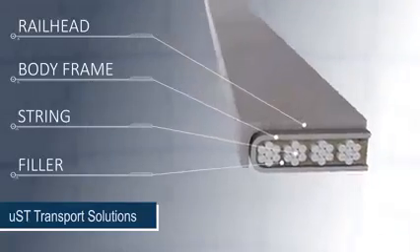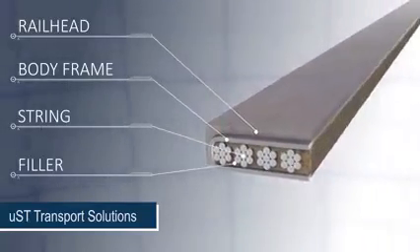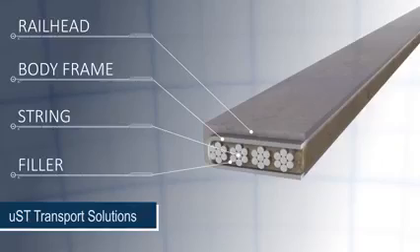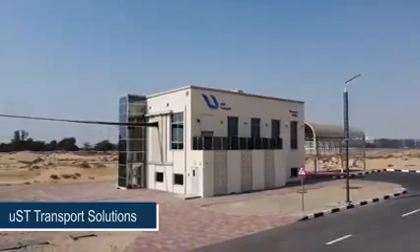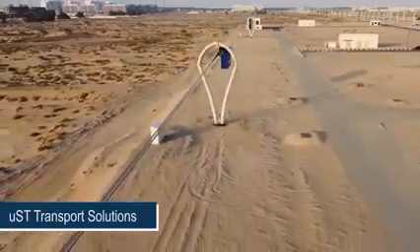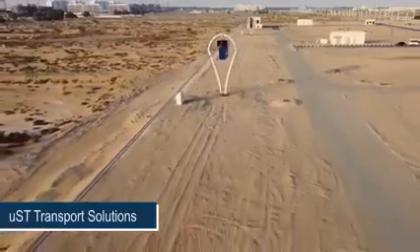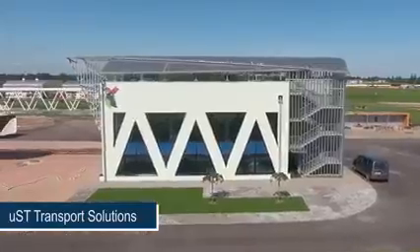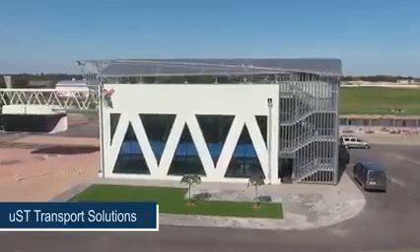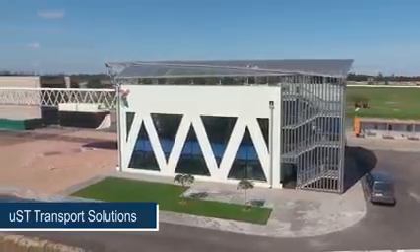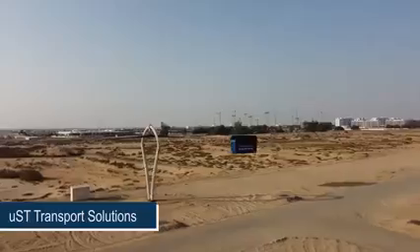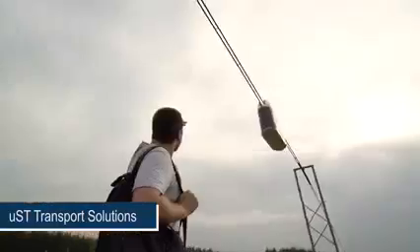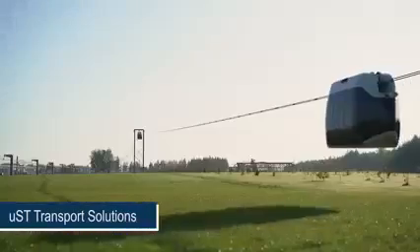It is a steel or composite beam containing a bundle of wires, strings, pre-stressed with stretching in its core and fitted with a rail head. The horizontal load from stretching is taken by anchor supports installed at a distance of up to 5 kilometers from each other. They can be combined with buildings for various purposes, including passenger stations and cargo terminals, as well as commercial institutions. The span between intermediate supports reaches 2 kilometers, which makes it possible to effectively overcome water barriers, pass over residential areas, mountain gorges, transport, or energy communications.